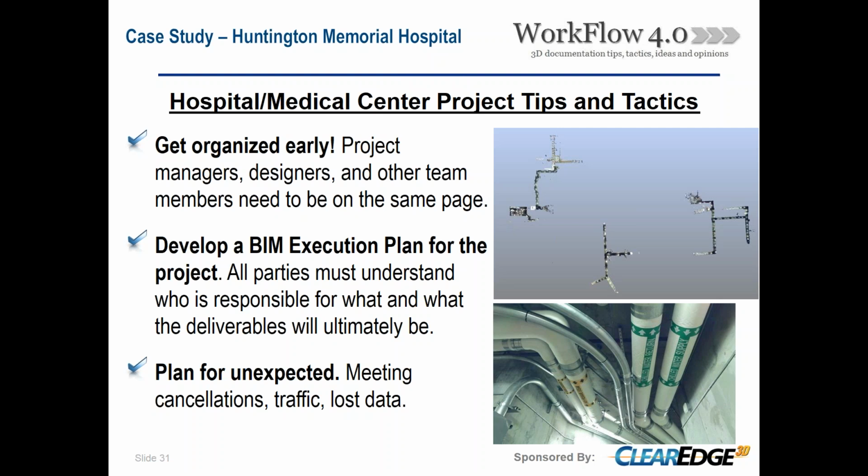It's good to develop a BIM execution plan for the project, which is guidelines and a layout of all the parties involved, stating here's what's going to happen in the project, here's what the deliverables are going to be, just so that everybody's on the same page. And it's good to get that early before you actually start doing the modeling, just so there's no conflict there. And also plan for the unexpected.